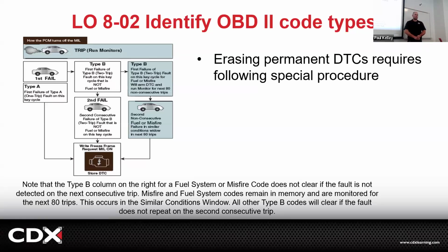How do you actually get this code to clear? Well, this is shown in the diagram. It failed. When you go to clear the code, it won't work. To get the code to clear, you actually have to have the monitor run and pass.